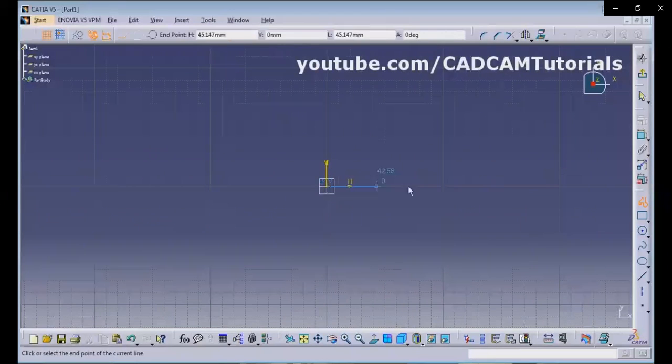Give the start point, second point, keeping it blue, so that blue means it is straight. If it is white, that means it is inclined. So pay attention that the color of the line is blue, that means it will come straight only. By keeping the color blue, click all the points.